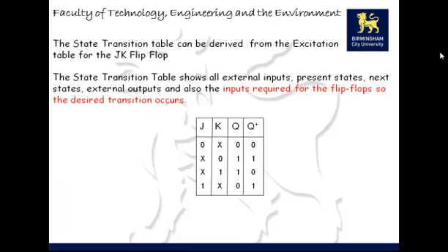Okay. Now, we've actually determined the state table from the Boolean expression. Would you agree? That's what we did. We determined the Boolean expressions from the schematic diagram of the digital system. From the Boolean expression, we obtained Q1 next, and that took 2 steps. First, there was a generic expression for Q next. Then we made it specific by substituting our expressions obtained from our digital system into the generic Q next to make Q1 next and Q2 next. From that, we determined the state table.